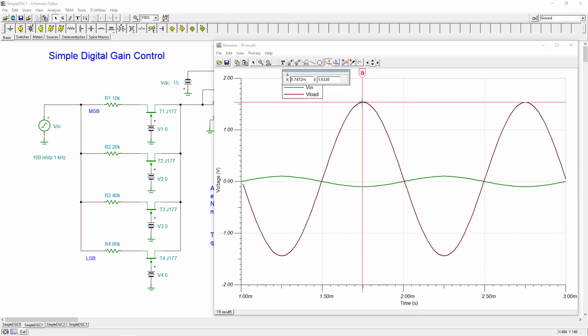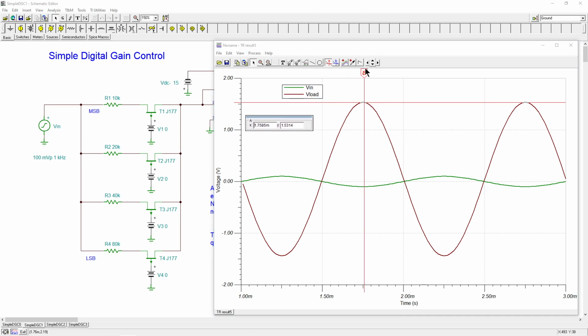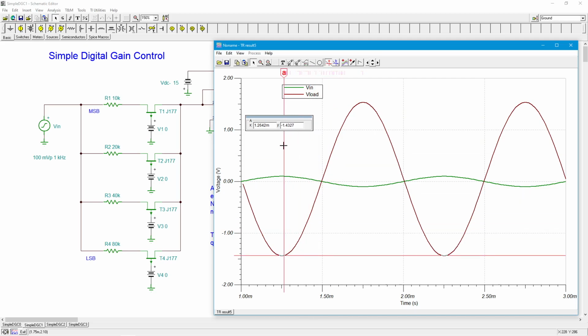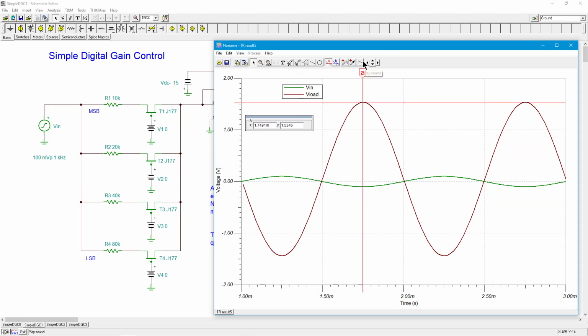And we can see that we're getting a nice big signal over here. So let's just go measure this. I'll move this guy over just a little bit. And so we're getting just a little bit over 1.5. But there is a little bit of a DC offset in here, I can see. If we come down to here, yeah, see, we're getting like 1.4 something negative. So there is a little bit of DC offset, but we are getting the gain approximately that we would expect. Okay? So that's good. I'm pretty happy about that.